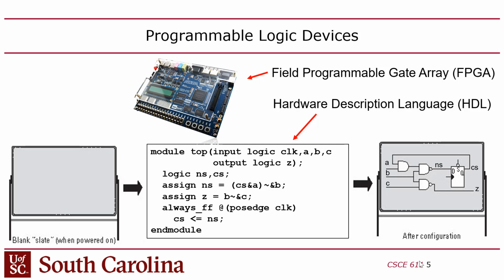And then the FPGA also has flip-flops in there as well, in addition to the LUTs. And then they have DSP blocks, which are hardware multipliers, and reprogrammable I/O pads. You might say, how can you reprogram an I/O pad? You can have them work at different voltages.